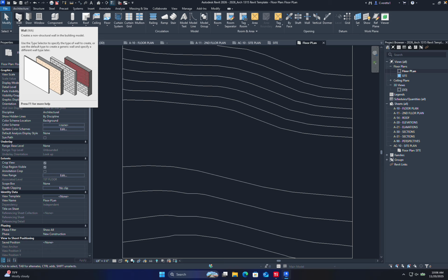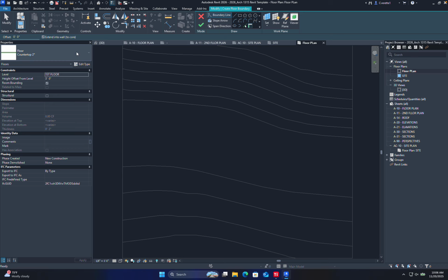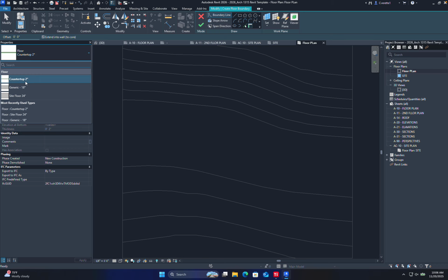Absolutely. So when in doubt, use your context clues and critical thinking skills on this one: Revit wants you to design or model it as if you were building it in real life. If you don't know how to do that, how are you supposed to work in Revit? Again, another reason why we don't introduce Revit in the first few years. But let's at least fake it till we make it and start off with some sort of floor. So let's definitely choose floor. And yes, I gave you some pre-made floors as well. Countertop, because that is honestly how I make countertops. I fool it.